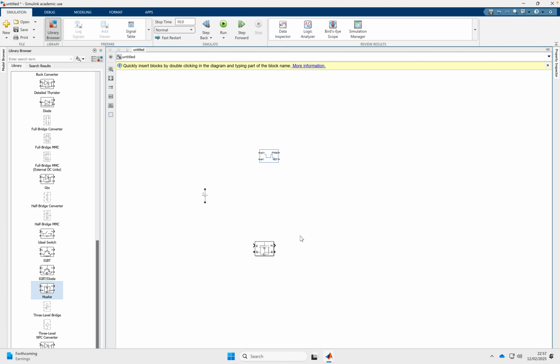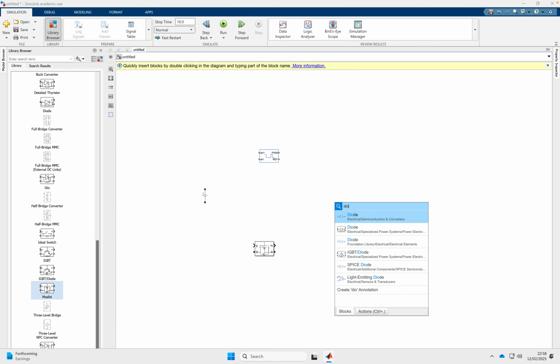It allows current to flow in one direction and offers high resistance in the reverse direction. So we found the diode under Simscape, electrical. We go to fundamental blocks and then elements. That's when we find the diode, or simply typing diode.